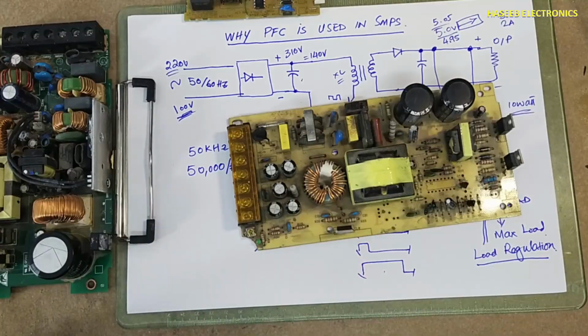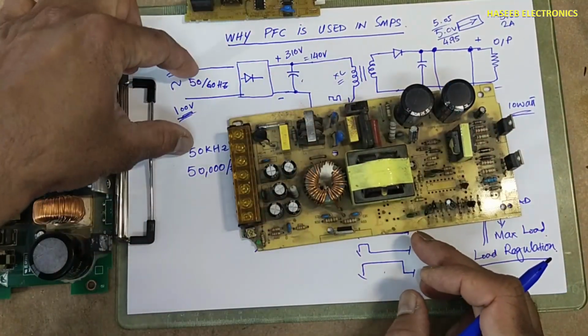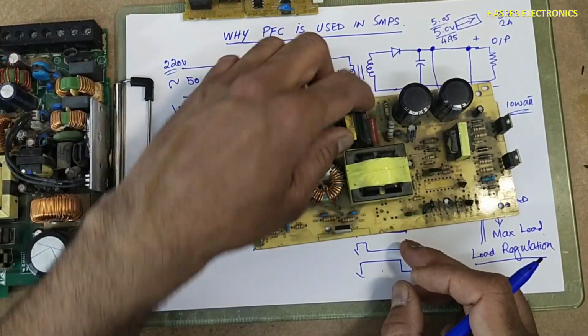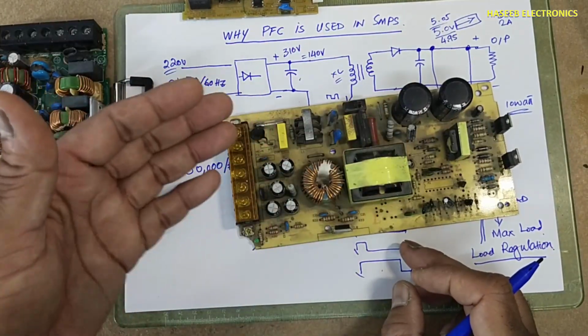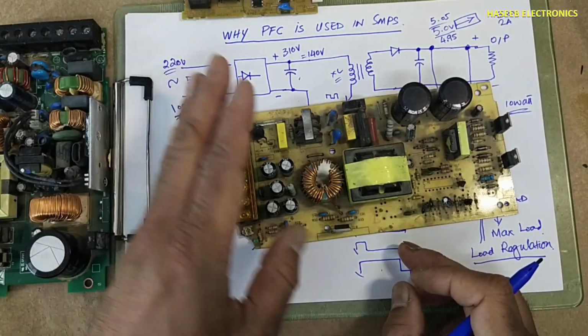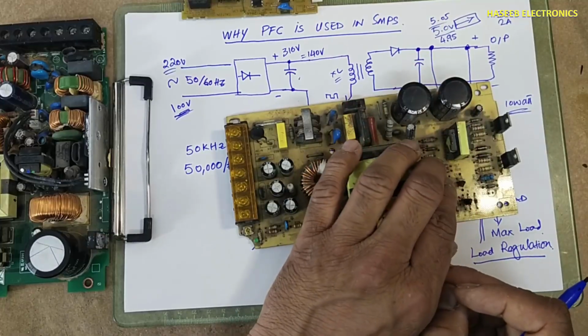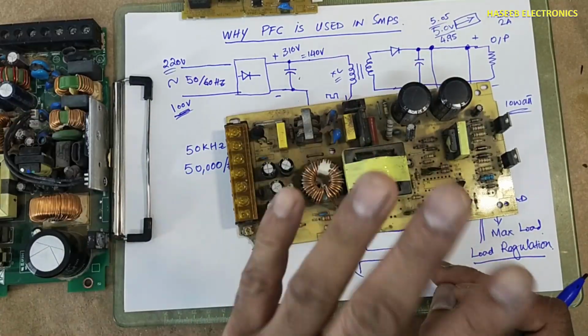If we see here, there is a switch to compensate this variation. If we are operating this power supply at 220 volt area, at that time maybe 185 to 245 volt, this PWM controller can adjust its duty cycle and it will provide regulated output.